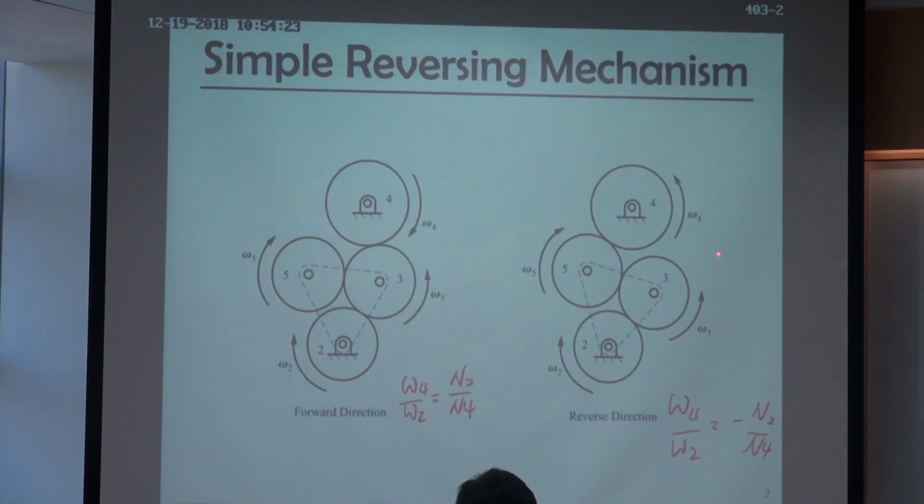So no matter how many gears you add into this gear train, you only influence the direction. Only the first and the last gears influence the gear ratio. The middle ones are not important actually; they only change the direction. This example uses multiple gears and a linkage, so you can do forward driving and reverse driving.